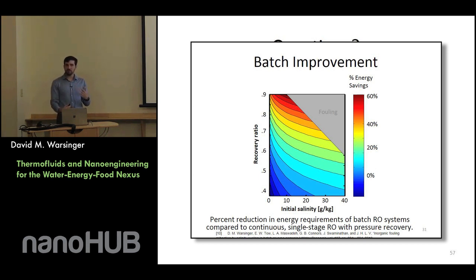It's still a small part of overall capacity, but at the low to the mid-high salinities, reverse osmosis is kind of the king technology. I will say that there are some technologies to which we have a healthy skepticism, one of which is capacitive deionization. The problem is it doesn't actually have a separating device, so you can just have back diffusion of your ions into the bulk. For it to really be effective, it needs to have an absorbing material that's selective, and perhaps its potential is in selective technologies. But for general desalination, it's thermodynamically not doing well compared to these technologies.